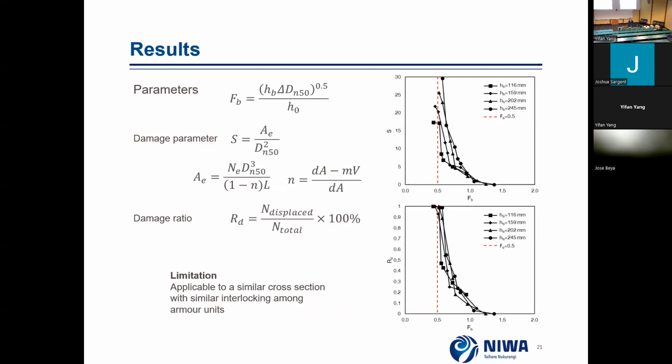And actually some other breakwaters are in muddy flat areas, which can be exposed. I guess what I'm trying to say is that we use a dry bed initial condition, mainly because of the recession before the first wave impact of the tsunami.